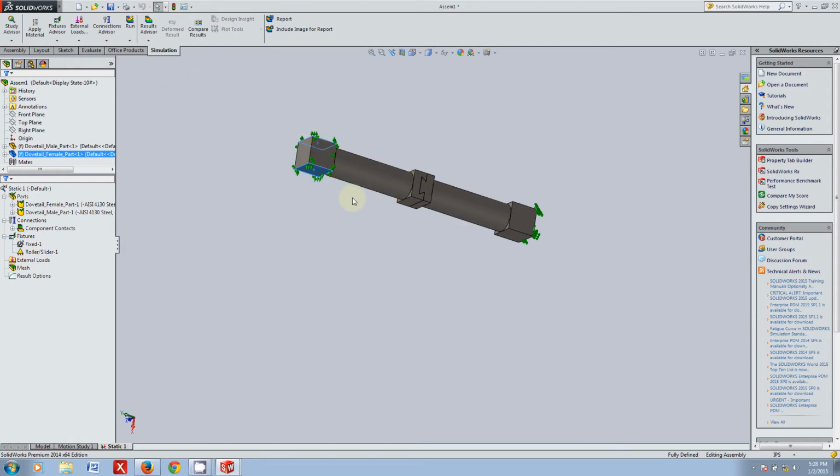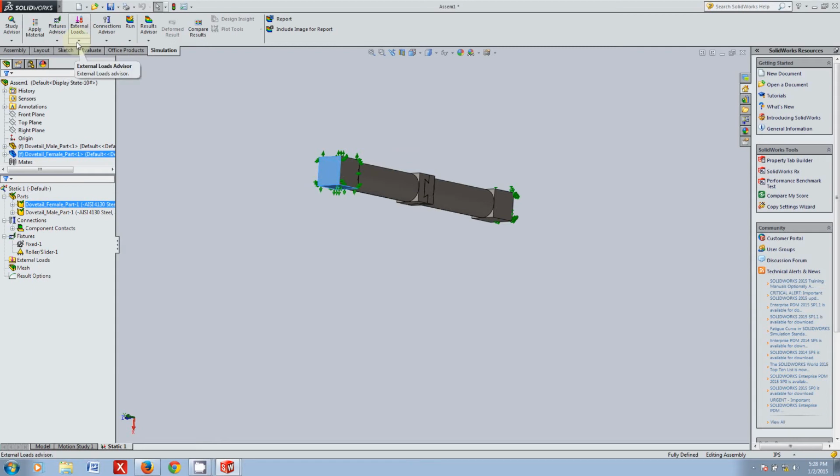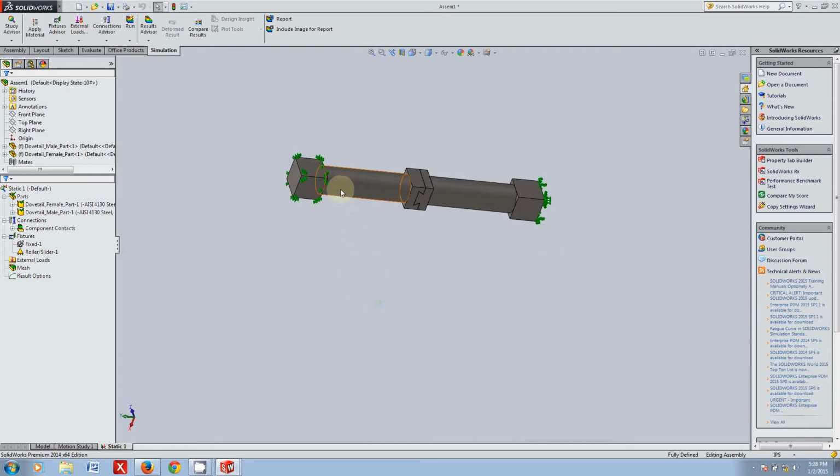That's precisely what we want for this next part, because now we're going to add a force to this end. You can select whatever force you particularly desire based on how you've set up your SAP model. Now in SAP you could go into a particular member and observe the actual axial force within the member.